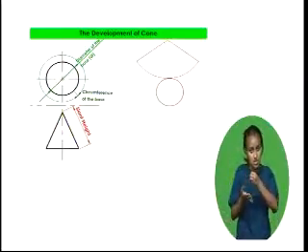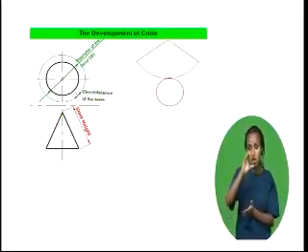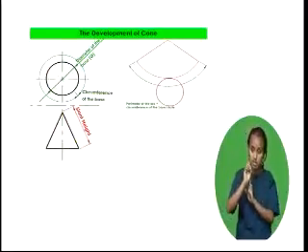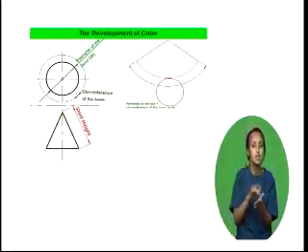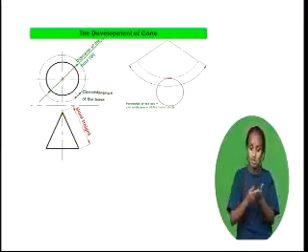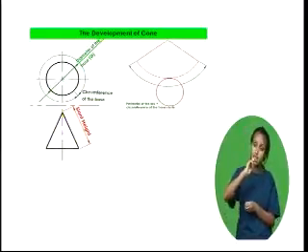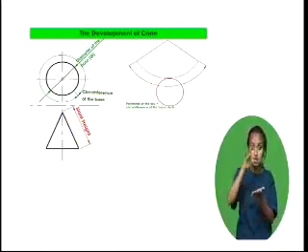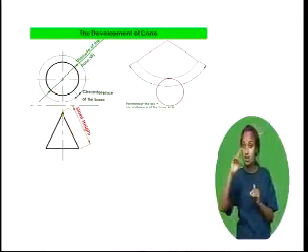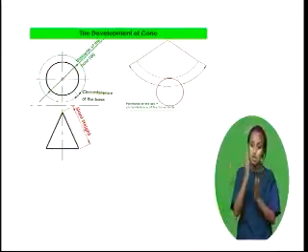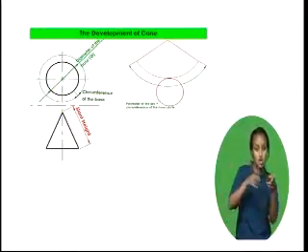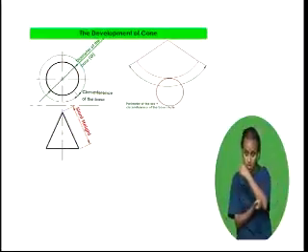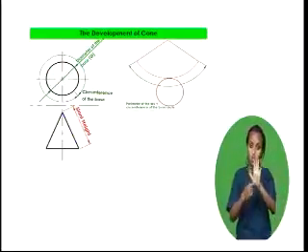For a right circular cone, the developed shape is a sector of a circle. The radius for this sector is the slant height of the cone, and the length around the perimeter of the sector is equal to the circumference of the base. The proportion of the height to the base diameter determines the size of the sector as shown on the screen.